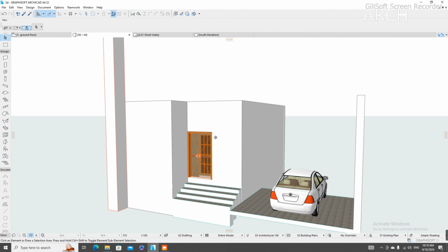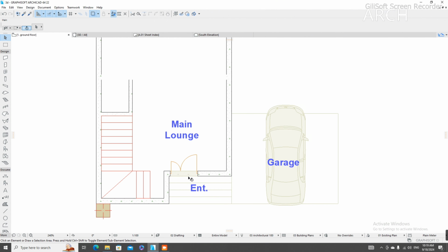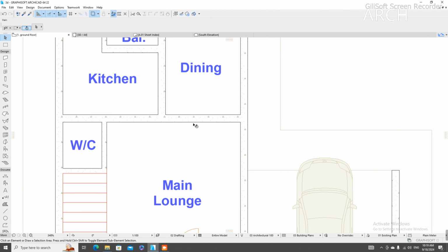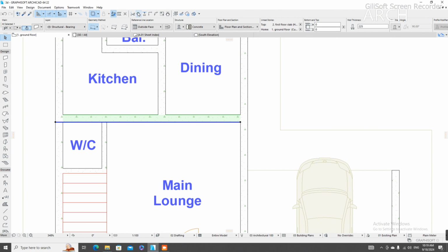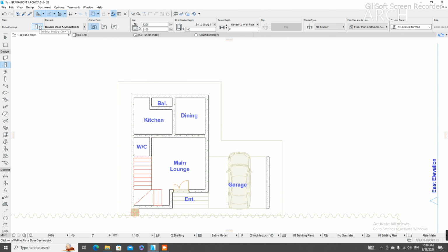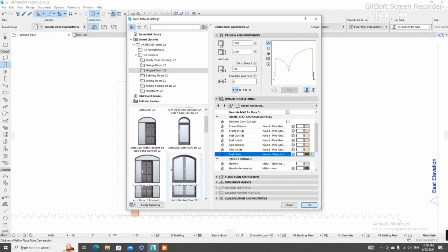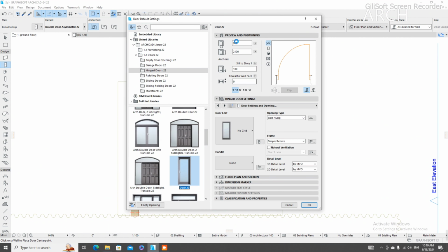So the next thing we need to go into right now is our inside doors. Let's check our inside doors. First we need an opening here, which means we need to split this wall. You come to the split tool, you pick this, or if you don't want to split your walls, you can use doors on that. Let's use a door on that, so it will be more professional. So let's come to this part. First let's pick our 900mm door.